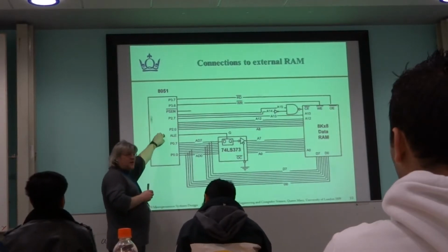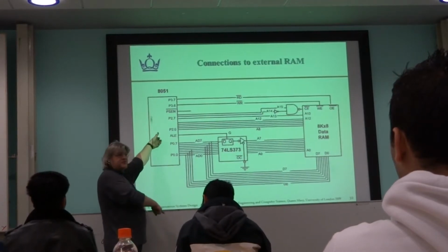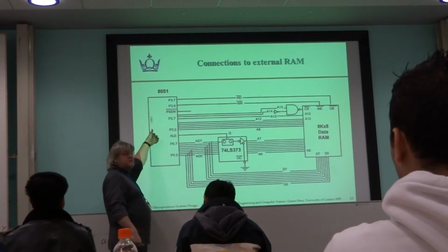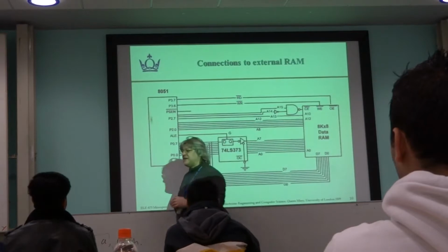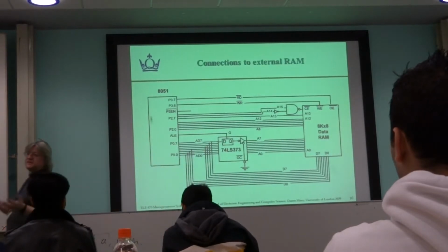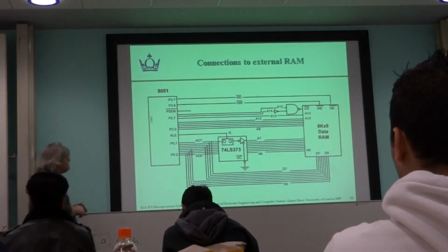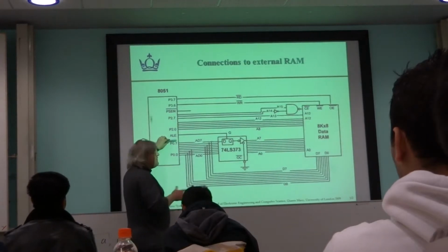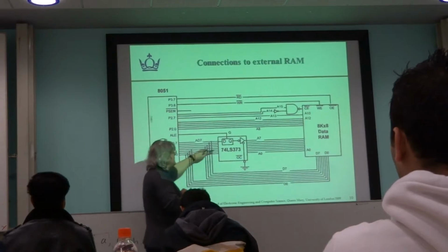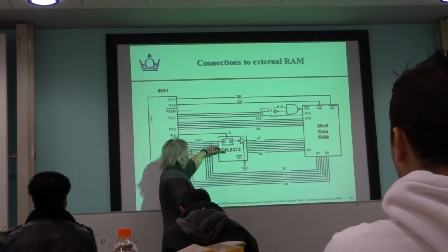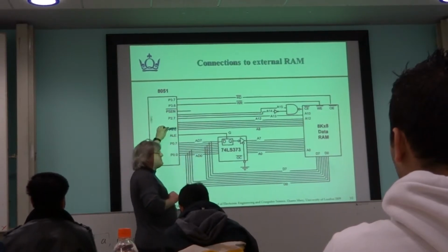But we're probably in our code somewhere going to be using these MOVX instructions. And because we're using the MOVX instructions, we've wired up all this external data memory here that could be holding temporary information. We've been logging the temperature of something, or I don't know. You wire it up in exactly the same way as you would for the other case. So port 0 needs this latch again for the demultiplexing. Port 2 provides the high part of the address.